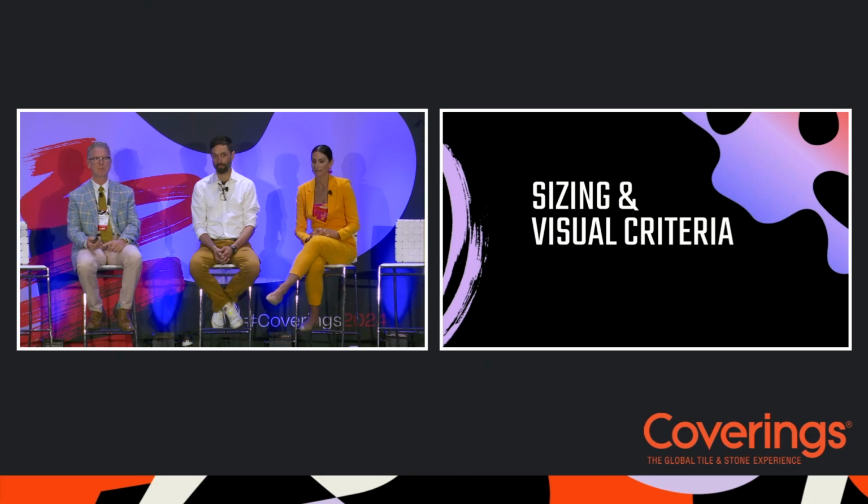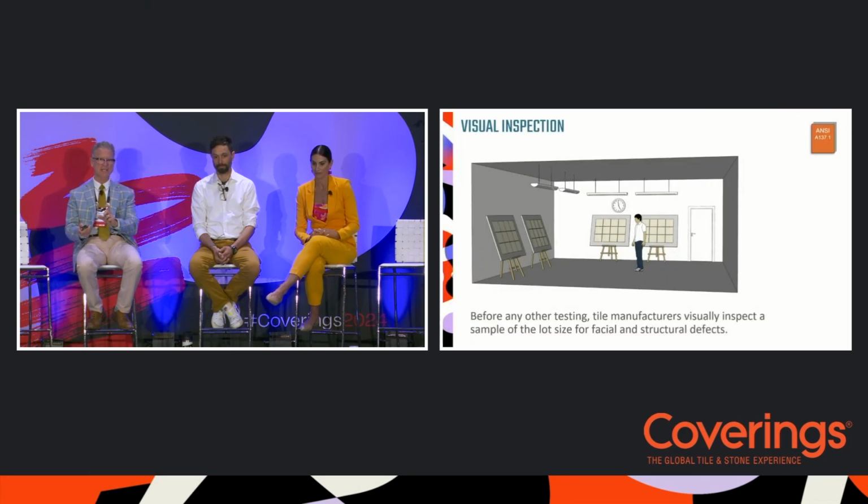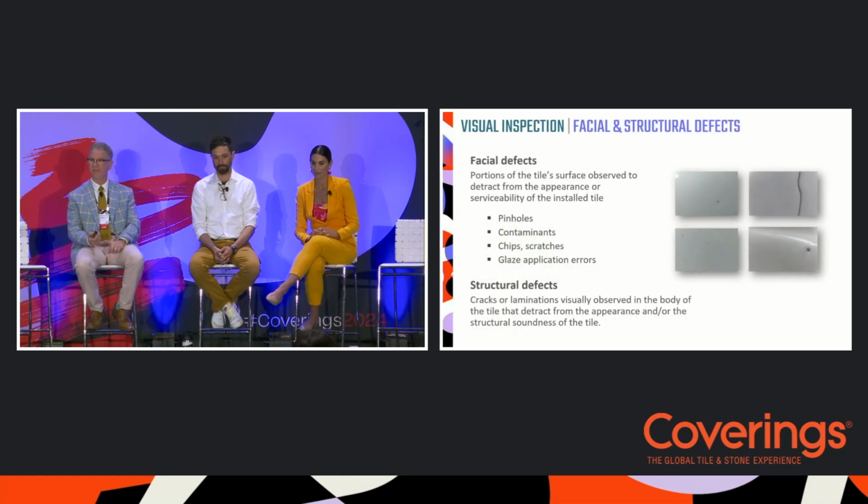All right, let's move on to something maybe a little bit more relatable. Sizing, edges, and visual criteria. So when a manufacturer makes these tiles, before they can ever package them up and sell them, they have to be looked at for facial defects and structural defects. If the tile contains structural defects, it cannot be sold. If it contains facial defects, it can be sold under certain circumstances. So what are these facial defects? They're pinholes, chips, scratches, etc.